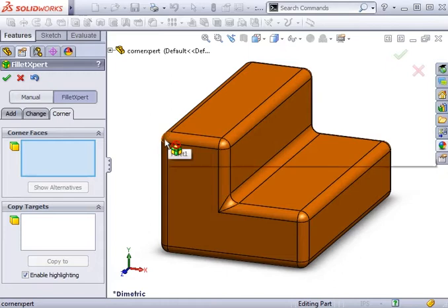There are really 2 classes of fillets. Some fillets that add material and some fillets that remove material. These are sometimes referred to as internal versus external fillets, concave versus convex fillets, or fillets versus rounds. For this corner, notice that the fillets are all rounded outward. However, the corner we selected earlier worked because it has a mix of internal and external fillets meeting at the same point.